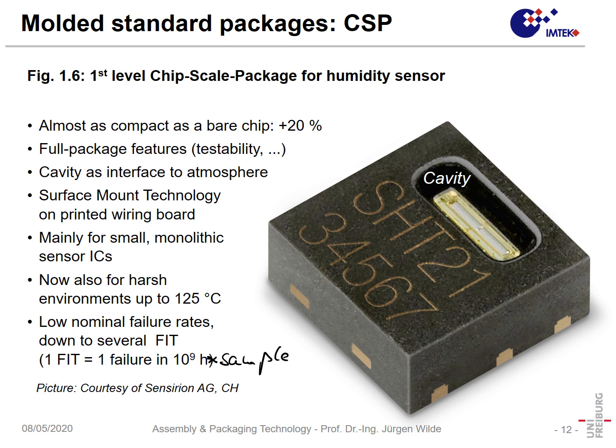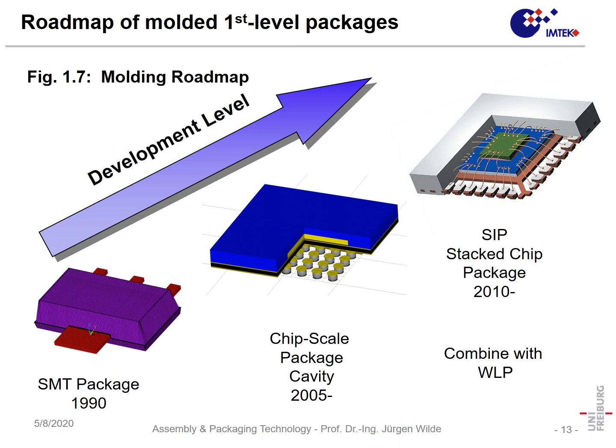Maybe complex processors go up to 100 FIT or so. So you have a guess what such devices must tolerate, and tolerate means, for instance, environments up to 125 degrees centigrade. For such IC packages, we have seen we had the molded packages, which have plastic housing here.